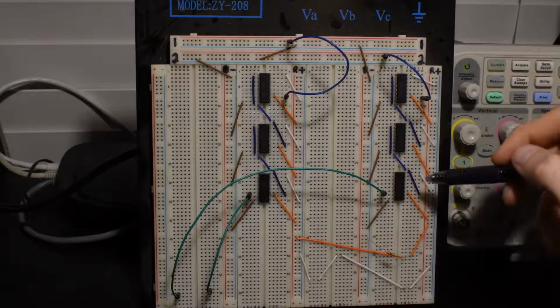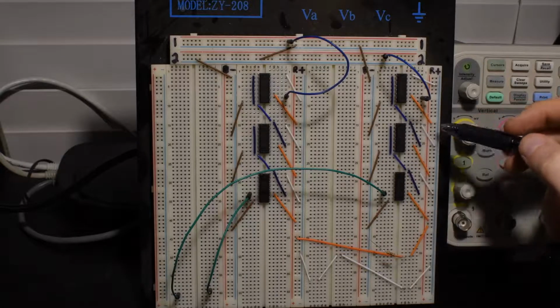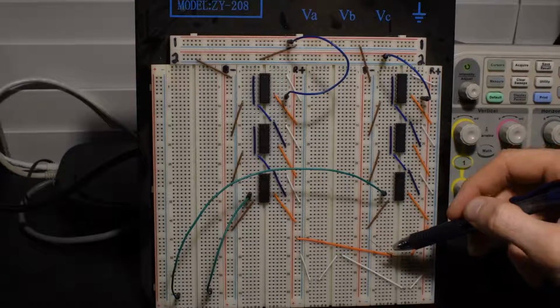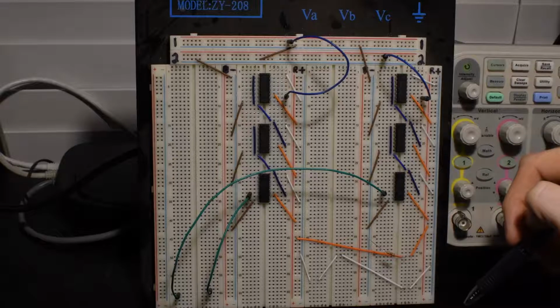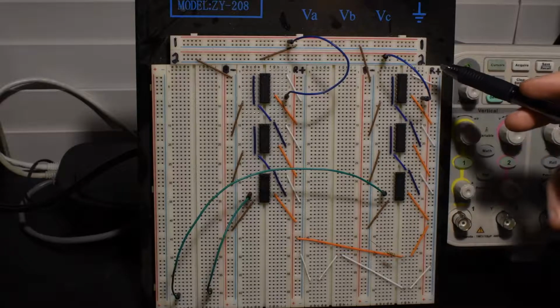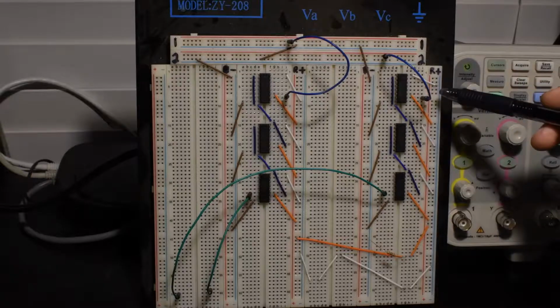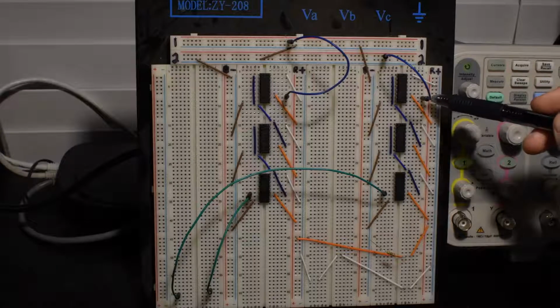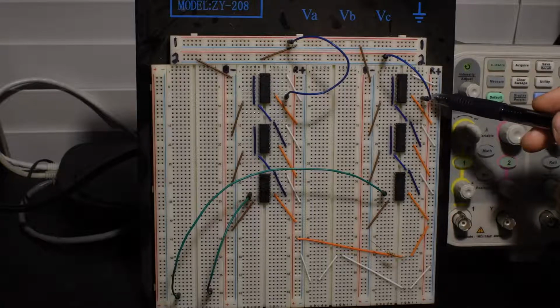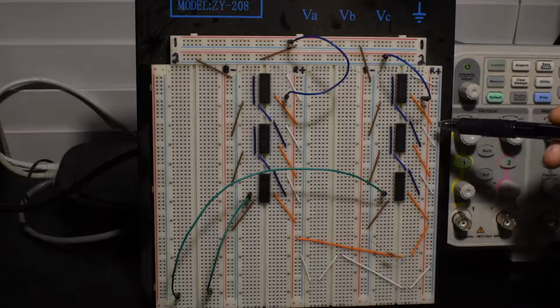By default, when there's no high voltage connected anywhere to any reset pins, this 50 ohm resistor pulls it down to ground, so that way, like I say, it's never floating. So the way this basically works is that the clock pin for each of these counters is the second from the bottom on the bottom right.